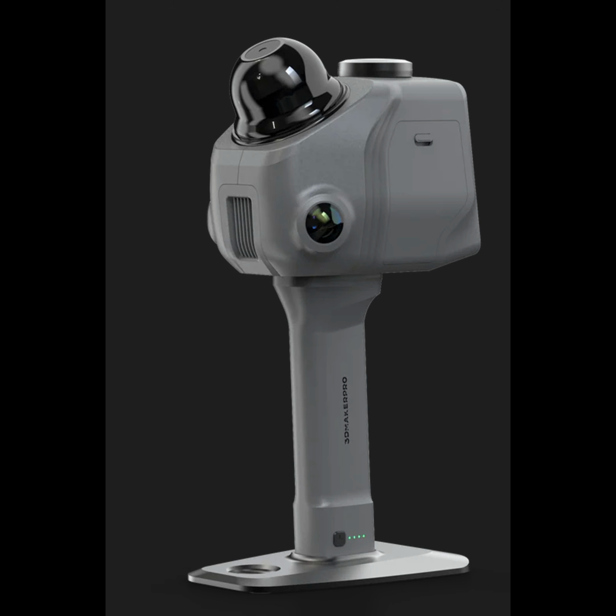So in this video, I'm showing a process that I developed that's kind of experimental to try to merge together a sparse point cloud from Agisoft Metashape. When it aligns all the photos, I align the fisheye images and then later split them into pinhole images for the Gaussian splat training. But using that Metashape-produced sparse point cloud, I merge it with a RayStudio-processed and exported colorized Lidar point cloud and initialize Gaussian splat training with that. The hope is that these flat walls that don't have any textures on them will train well, and the Gaussians will be locked onto those points.